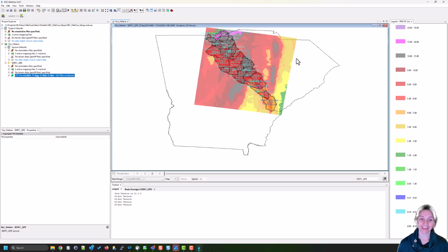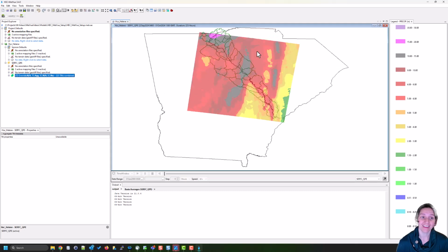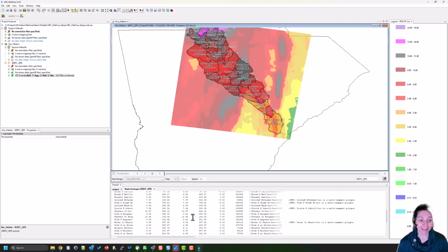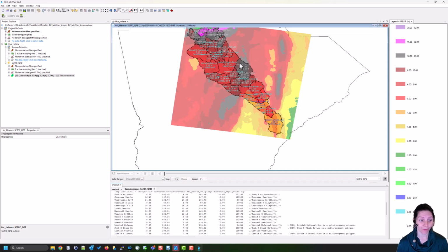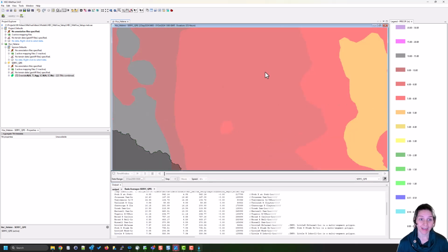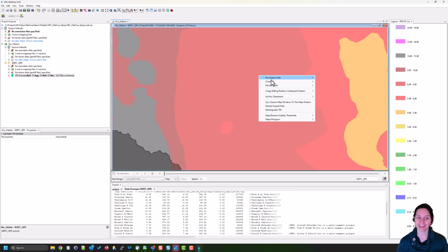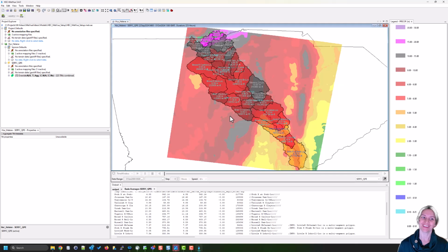You have created your very first MetVue project, and you have imported data. Down here at the bottom, you can see the calculated basin averages for each individual area. Another thing, if it doesn't automatically zoom and you want to zoom back out, you can right-click on the page, click Zoom To, and zoom to subbasins reprojected. There we go. So all of this data, these are the subbasin averages for the entire period that you're looking at.